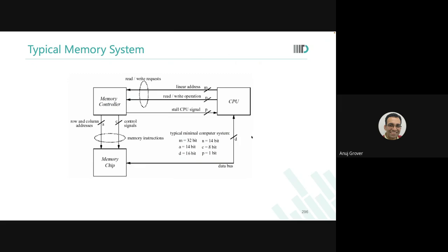There's a coprocessor that handles all the interface of the DRAM with it. And the complexity of the on-chip caches is such that you have to put a separate controller there. So as things are scaling, more things are getting packed. We have a memory controller which does all the interaction with the microprocessor, and the DRAM never actually practically interacts with the microprocessor directly.